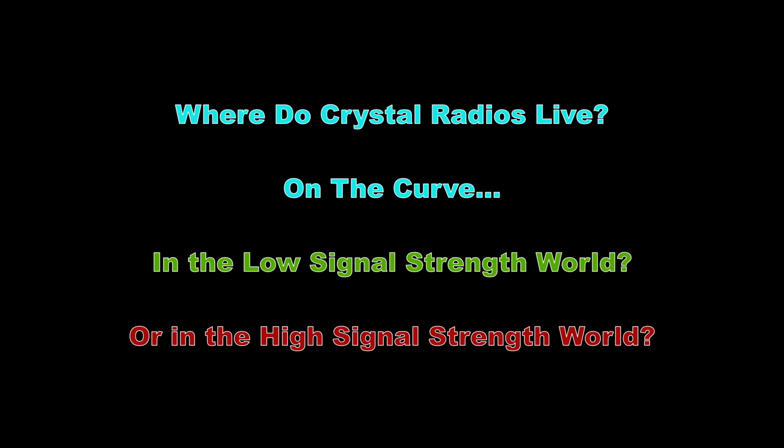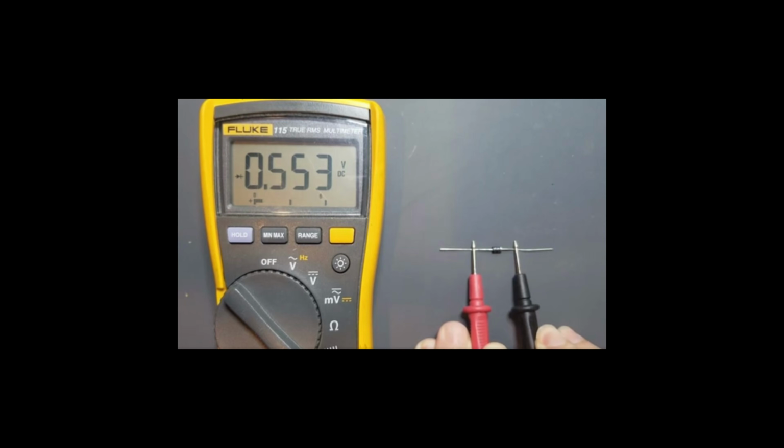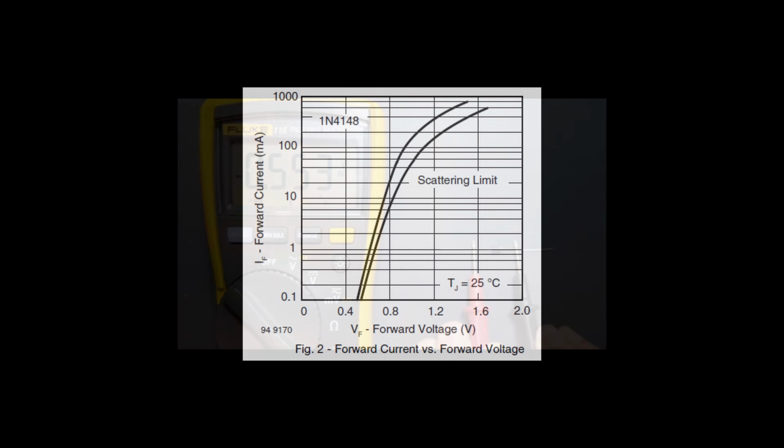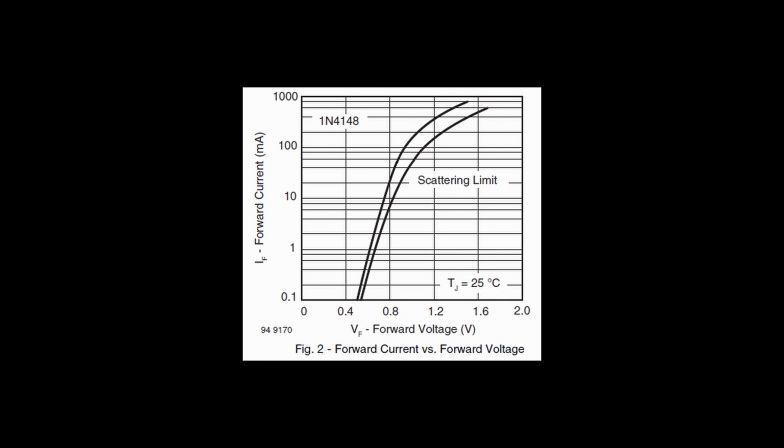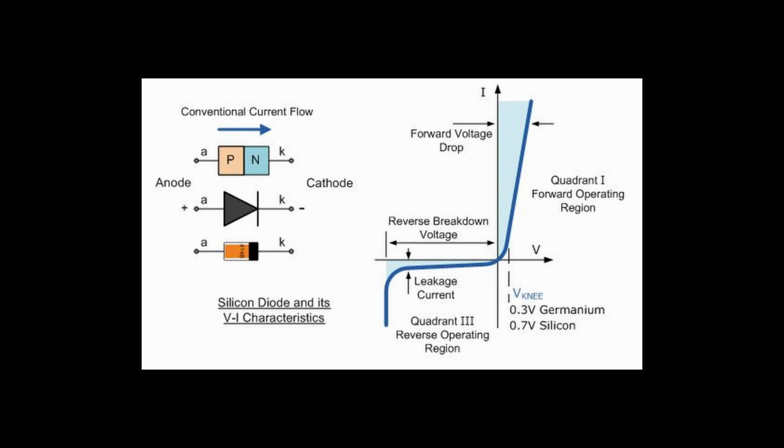And let's clear up a little confusion about diodes. When we measure a diode with our meter using the diode function, we see a forward voltage of, say, 200, 300 millivolts. It's very tempting to think that the diode's not turned on till you hit it with that current that produces that forward voltage. Well, that's kind of silly because we know that most signals hitting our signal diode are well below 100 millivolts. In fact, they're below 1 millivolt. And yet we hear loud signals in our earphones.